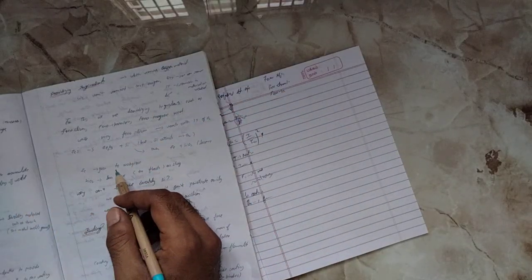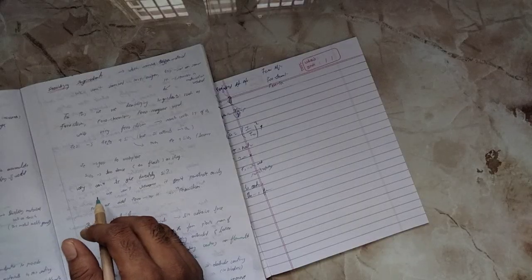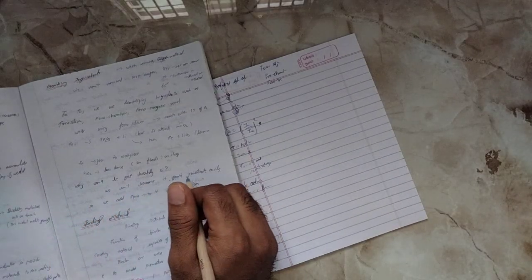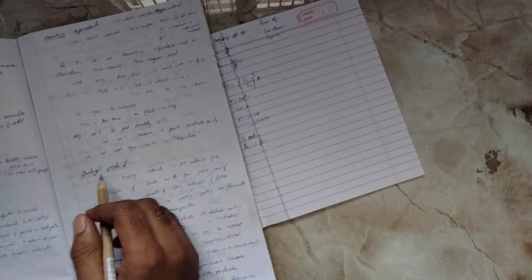The silicon attracts the O2 and it comes outside, and the Fe goes to the workpiece. You may have a question why we can't use silicon directly. We can't use the silicon because it can't penetrate easily, so we add ferrosilicon. Okay, next one is binding material.